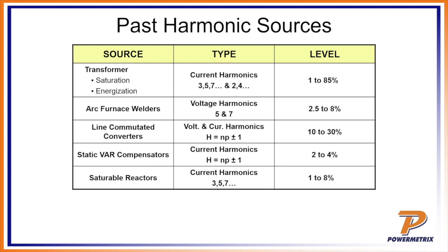If we take the example of a PT, potential transformer, instrumentation transformer, when you buy a PT, it's got a VA rating, that's its power rating. Basically that PT has to power everything on the secondary side of that, which most of the time is just the meter, but of course if you have other equipment on the system, it has to power that as well.